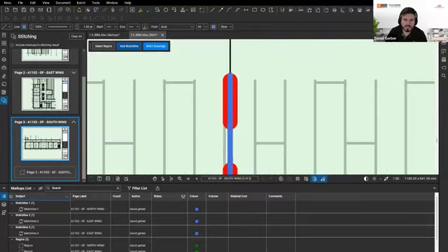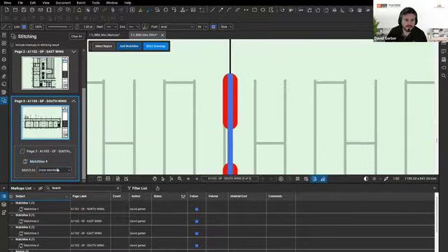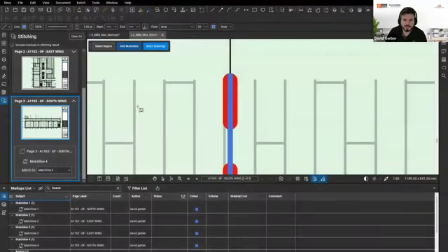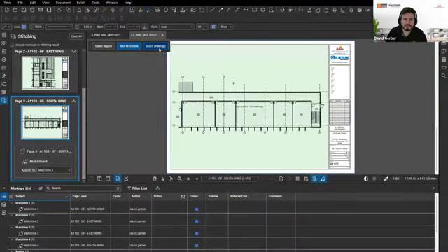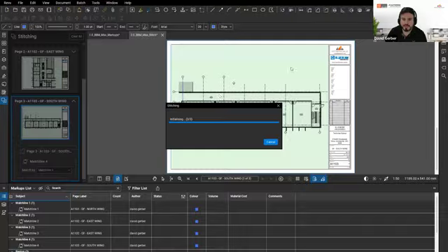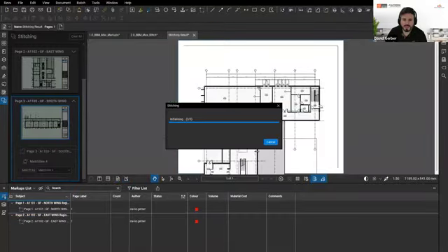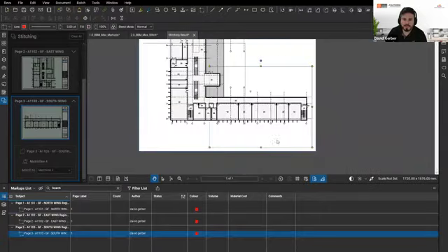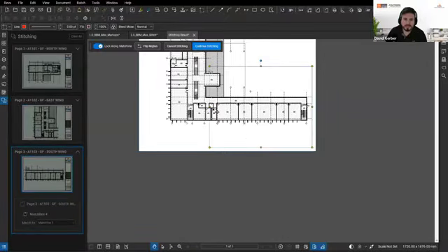And it's going to help you and say, hey, these are not matched. So you can see it's not matched to page two. So I can pick that one or I can change them if I need to. But then from here, I can just say, go and stitch the drawing. It's going to try and do its thing. If I wasn't accurate, which I did on purpose here, you'll see that it gives you this warning, which is fine because you can still move it.